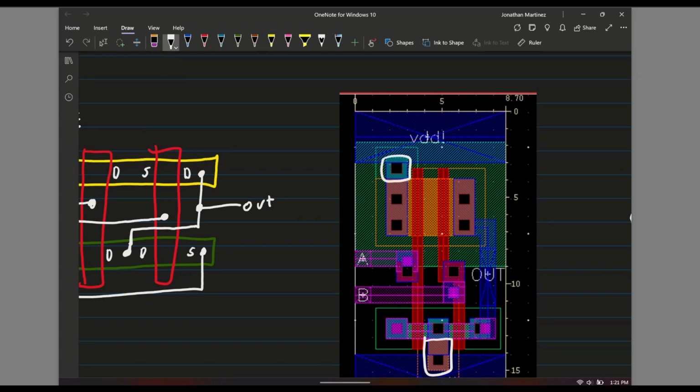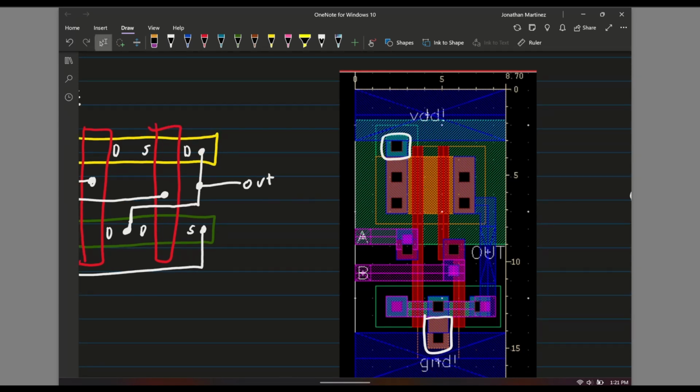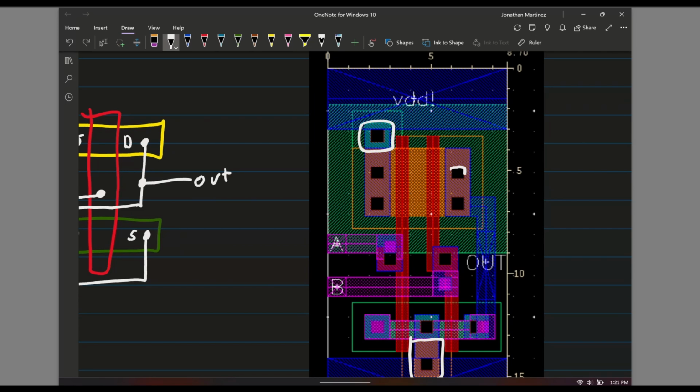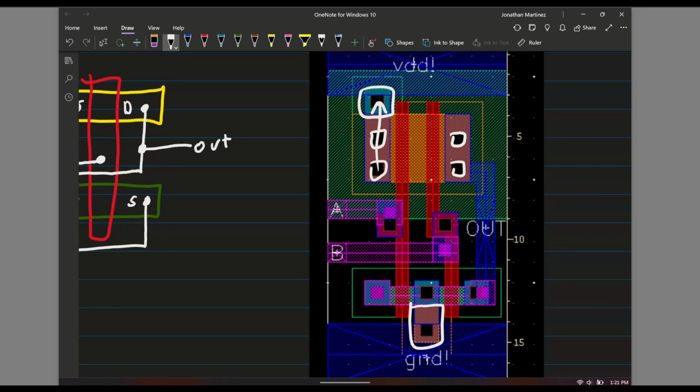Technically you could customize this quite a bit, as long as you're consistent. The other thing that they have is several contact pads from the metal to the P region, and several contact pads here from the metal to the P region that goes towards the voltage source. And then these two contact pads connect to this metal, which then goes to the output.